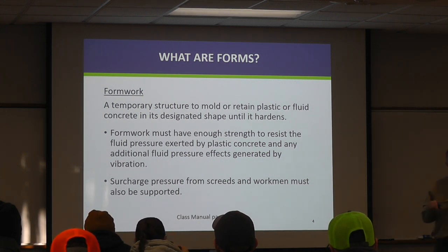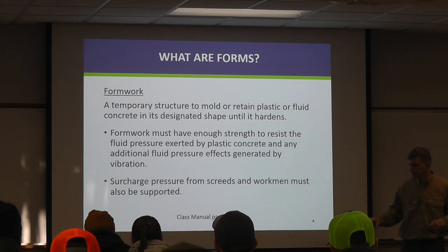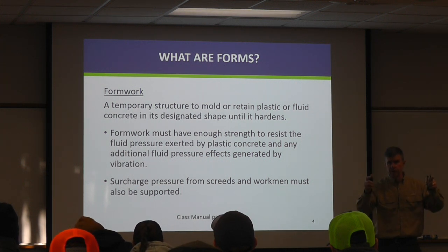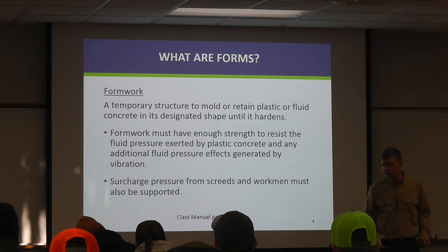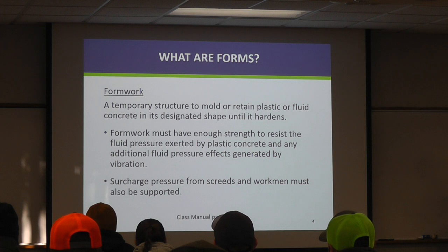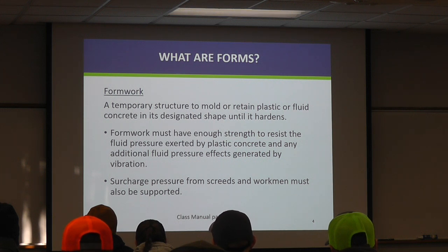The bridge design plans do not tell the contractor how to construct the forms. Bridge plans only say build it to a given dimension and so forth. So it's up to the contractor to design the forms, and then the falsework we'll get to in a few minutes. They also have to then account for any additional pressure from screeds, from workers, everything has to be supported.